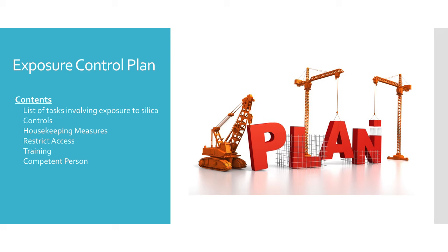The new rule requires the following contents to be in an exposure control plan. List of all tasks involving exposure to silica, a description of how silica dust will be controlled, housekeeping measures that will be taken to reduce dust, how the employer will restrict access to only trained employees, thus protecting other workers